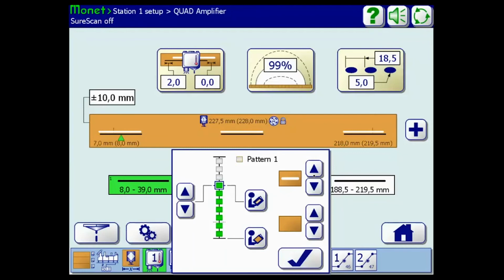With the sensor mounted above the product, you can measure not from the bottom, but from the top of the sensor to the product. I would set that at 95 millimeters, and we'll email you an electronic copy of documentation that specifies this too. But from the top of the sensor to the product, make sure that's 95. And then the little plastic cap you can thread onto the bottom of the sensor, so there's approximately 20 millimeters between the bottom of the cap and the product.